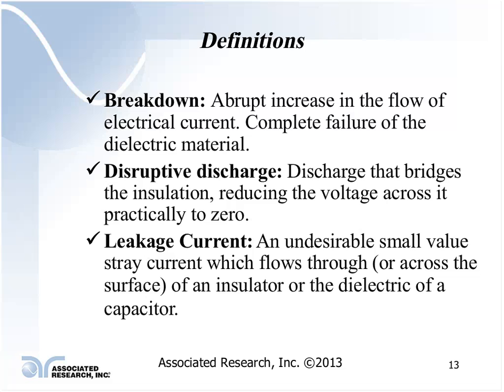Again, where do you set your trip point? A good rule of thumb is to set it to something slightly higher than what your product would normally draw. Check your safety standard. Make sure that you are testing in accordance to the standard.